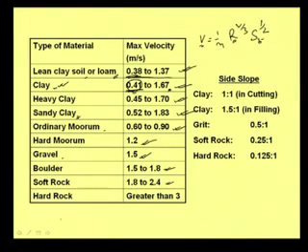From experience and from experiment we can find out this sort of value, and these were given as suggestions, like for clay we can go for a slope of 1:1 if it is in cutting. What we mean by cutting, as I was explaining: say suppose natural terrain is like that, and we want to make a channel to carry water from this point to this point. Now it will be difficult to go like that. So what we will do, we will make an average slope like this from here to here. We are filling up this portion, and suppose this formation is clay.